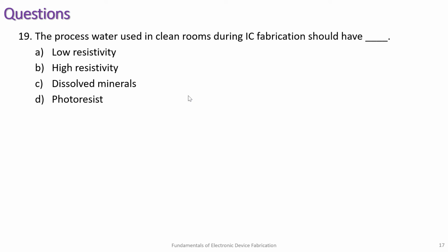In wafer fabrication, like I already mentioned, we had one question where we discussed the metals that are present in chemicals, right? So we are actually dealing with very small materials that have dopants present in very small quantities. And very much care should be taken that no processes or properties will change the mobility or electrical conductivity of our particular wafer or chip. Whenever we are using water that has dissolved minerals, the conductivity will be altered or increased, and this will destroy the functionality of our chip.